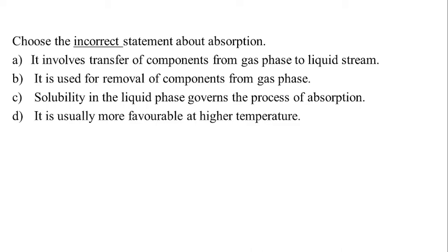In fact, you'll always prefer to select a solute which forms a weak bond. Why weak bond? If you have a solute which absorbs very well but forms a permanent product because of the chemical reaction, you cannot liberate the absorbed component again. It takes a lot of trouble later on, possibly boiling at a much higher temperature if you have to liberate it. But if it is a weak chemical bond, for example, your CO2 forms a very weak bond with the H2O which is there.